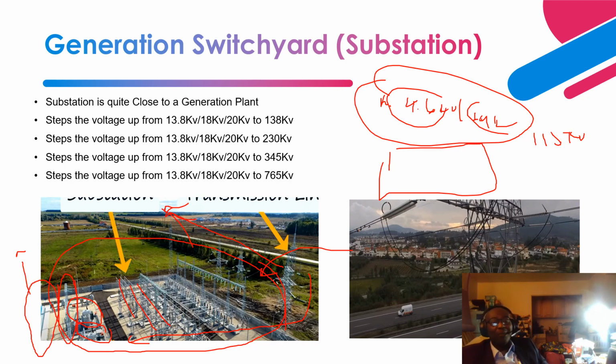And just to name a few, what are my auxiliary equipment? Boiler feed pump, heater drain pump, condenser pump, motor, all these motors, and if you have a coal plant, you have pulverizers, right? That basically grinds the coal into different powdery form, right? So basically we have this medium voltage level that is required by all these auxiliary loads. So for you to start a power plant, right, you need an auxiliary source.